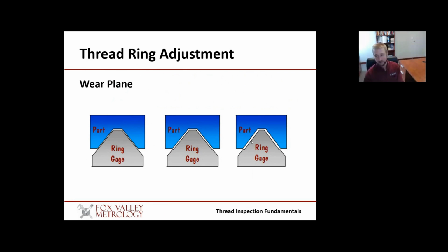But fortunately, for adjustable rings, we can, of course, worry about this step that's being built into the ring gauge itself and adjust it so that way the ring gauge is brought back into tolerance. Of course, for plugs, that's not an option for us. So once plugs are worn out, they simply just need to be replaced with a new member for the size that you're looking at.